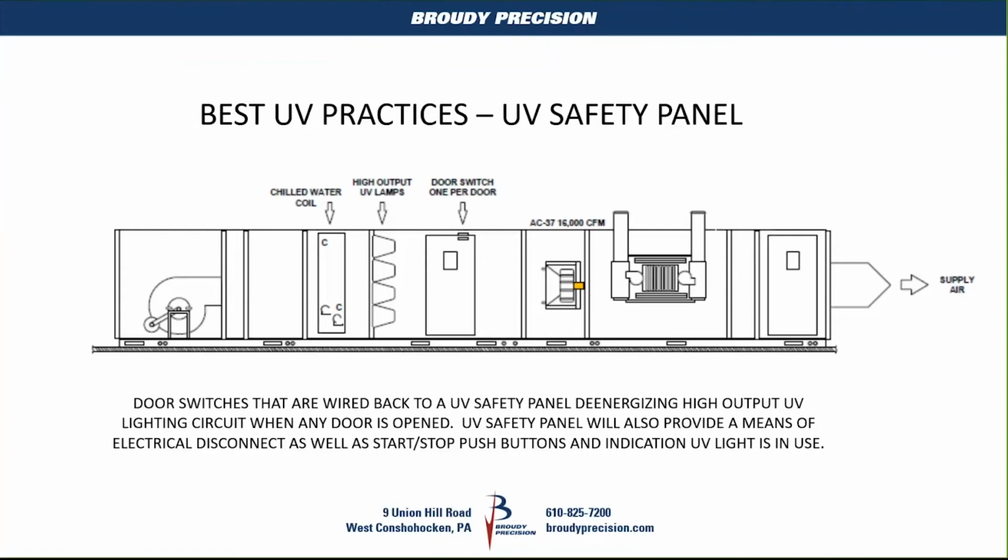UV safety panels also provide a means of electrical disconnect. So main power is brought to this panel and the distribution to the racks is from this panel, but we provide an electrical disconnect on the face of the panel, as well as start-stop buttons to turn it on and off manually, as well as indication, so you don't have to open the door to see if the light's on.